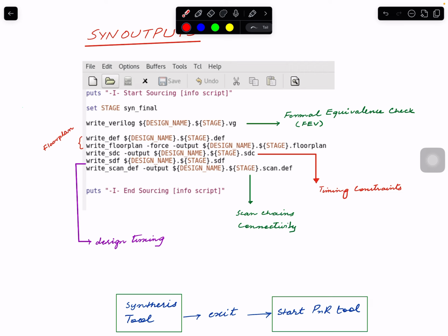So prior they were just doing a very idealistic simulation, but the netlist has gates, has standard cells, and they have delays. So if they want to do a gate level simulation of the chip, that will take a lot of time though, because now we have all the delay information. But maybe in some critical stages, it makes sense to do that. Or maybe for smaller chips, we can do that. Or maybe in the DFT part, we can do that. Maybe ATPG too, I haven't run that myself. Probably that needs it. So anyway, there are customers of SDF files. That's why we generate that.